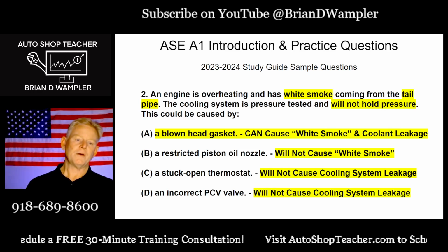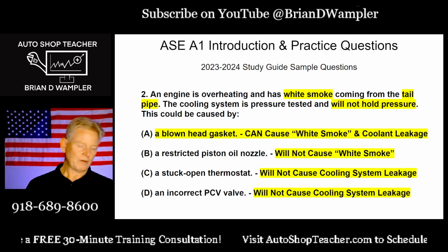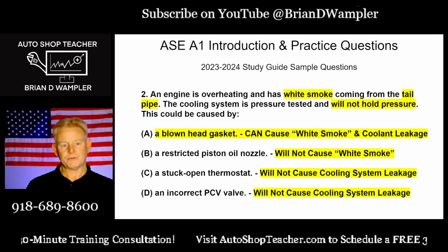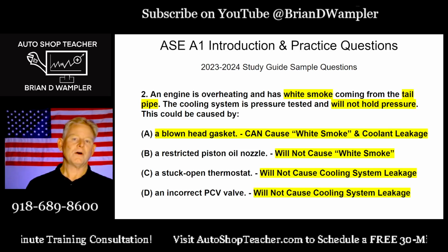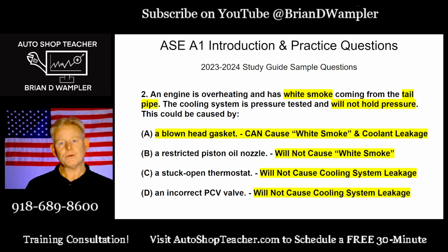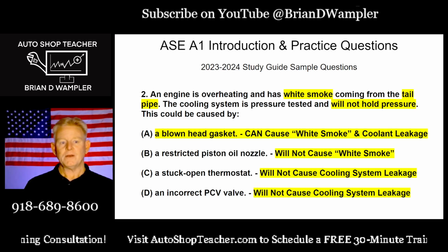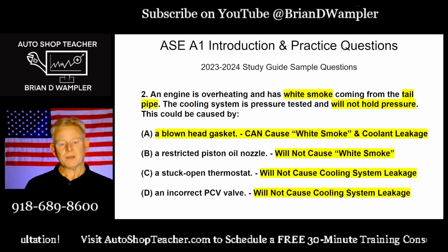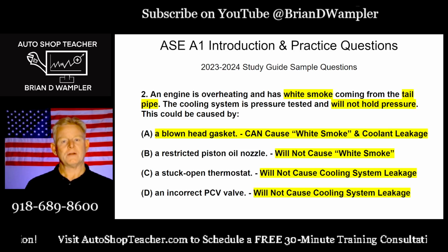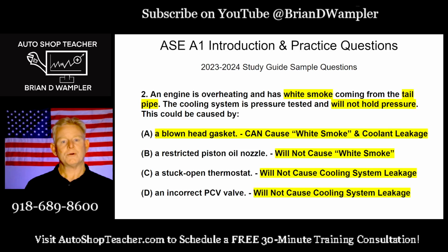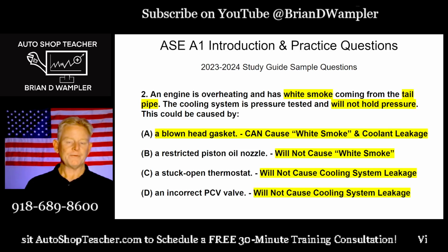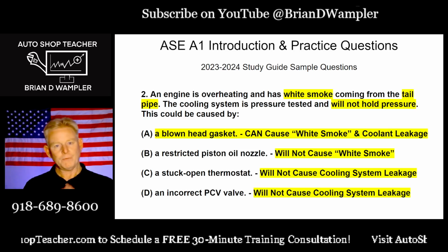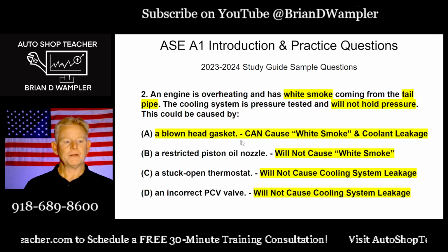Now, what are we talking about with white smoke? In automotive diagnostics, we generally deal with 3 different colors of smoke. White is most often associated with the burning of coolant, antifreeze, or even water. If it's very diluted and it's mostly water, it'll still be white smoke, but it might look like steam and it might dissipate much more quickly, where coolant antifreeze will leave a much more lingering cloud in the shop that hopefully you get blown out the door pretty quickly.